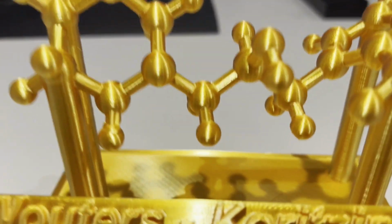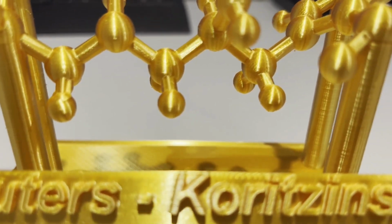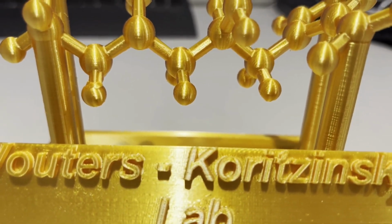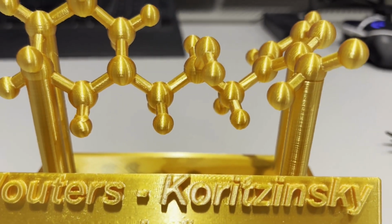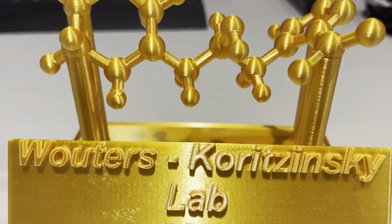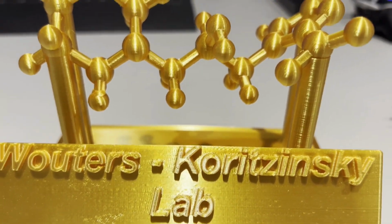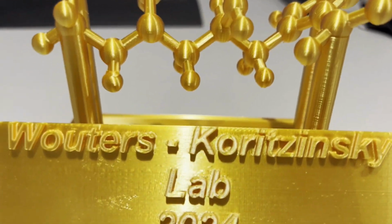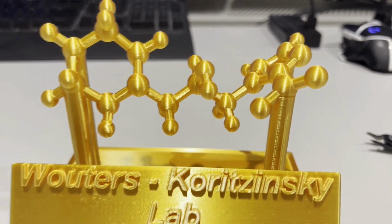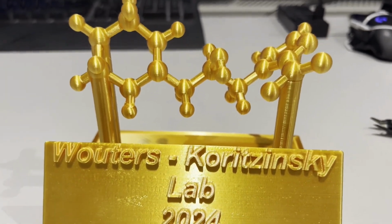The part that actually kept failing the most was right when it started printing these lower hydrogen atoms. Because of the poor surface area contact, I actually had to increase the interface density as well as the general support density overall. Because if one of these balls comes loose, it'll start rocking around throughout the print. It'll snag on the nozzle. Once it snags on the nozzle, it'll start knocking over other supports and other parts of the model, ultimately leading to a catastrophic failure.